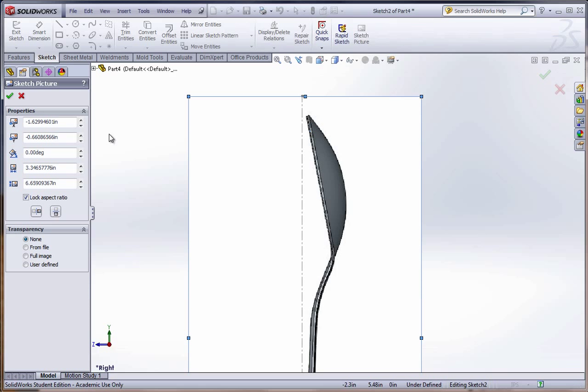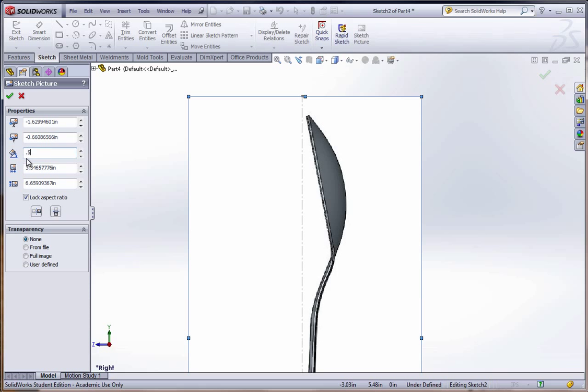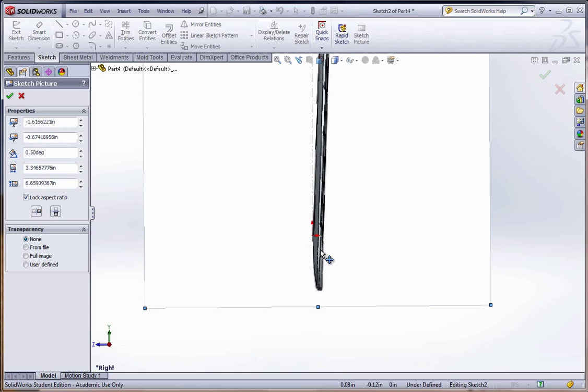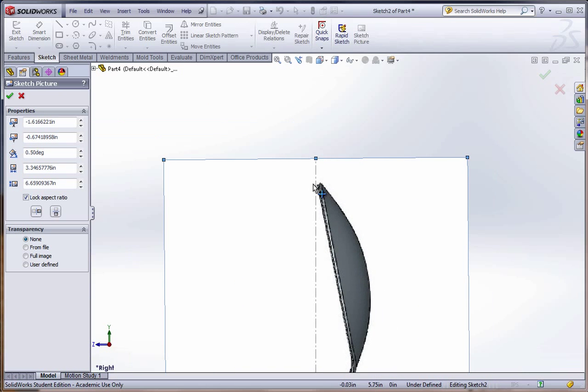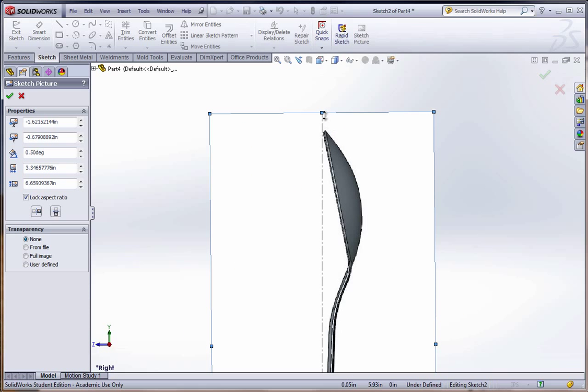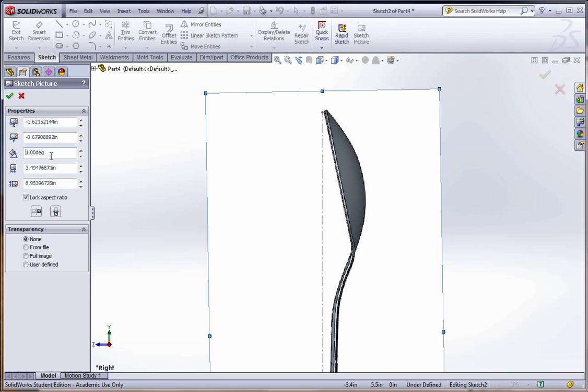And then we could rotate it so it contacts this. Over here there's actually a rotate, and if you hit the button, 1 degree is just too much actually, so we probably want 0.5 degrees. And just again double check to make sure it looks good. Drag it in just a little bit more. Oh, actually I still have more room here. So I'm going to drag this out a bit further. Let's change it to 0.7. Yeah, maybe 1 actually would work. There, 1.125 degrees seems to be.